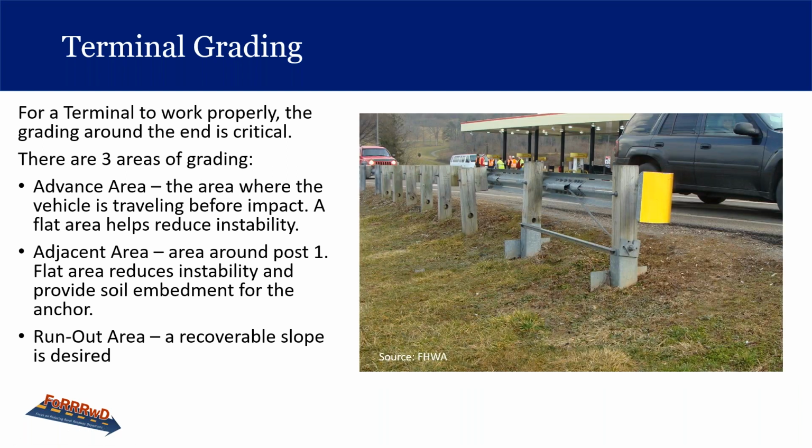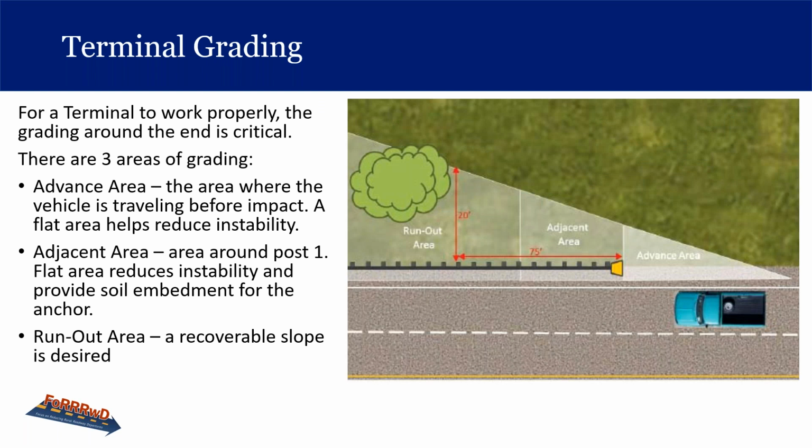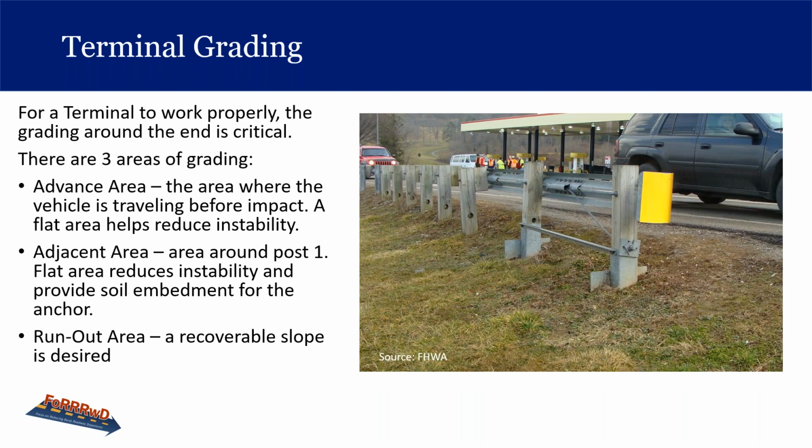Let's see here. Thought I had some animation there, but if you can see the soil plates and space under the strut, the grading is not correct. In this case, the anchor may not be able to develop the strength of the system. Because the posts are too high out of the ground, the vehicle may not break off the posts, or they may snag on the stubs. This installation may not work for either purpose for the end treatment.